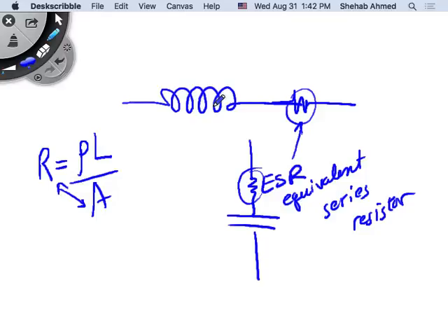But with a big diameter, you still need a certain number of turns to design an inductor. We will talk about that a little bit down the road, but bigger wire means bigger size. Bigger size means more copper. More copper means more expensive. So it's heavier and more expensive, but it's much more efficient. Right? So it's a compromise.